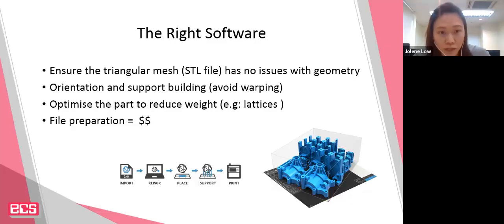Second point we want to bring in, in terms of SLA and DLP printing, we have a support creation that is required to avoid any warping or any effect on the part itself. So that area of support creation, how long it takes in the software and how easy it is to actually build your support, is a great deal. Which brings me to my last point, which is file preparation. The ease of use of the software actually allows you to save on man-hour labor costs, and that is a great deal in terms of how 3D printing is moving into production.